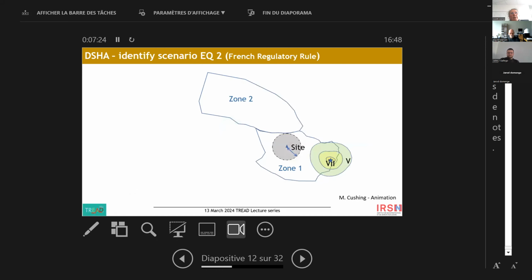site. Now, if we take the other event and we do the same thing, we try to draw isoseismals. In this case, it comes straight underneath the site. So you understand that for this particular event that comes straight underneath the site, it's going to be very important to evaluate not only the magnitude of the event, but also the depth, which is a bit challenging given the data that we have.